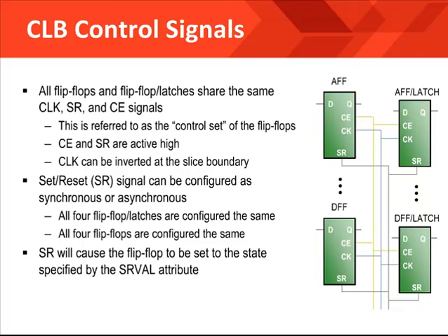The set and reset signal can be configured as synchronous or asynchronous. For synchronous design purposes, Xilinx recommends that unless absolutely necessary, you design with a synchronous set or a synchronous reset.